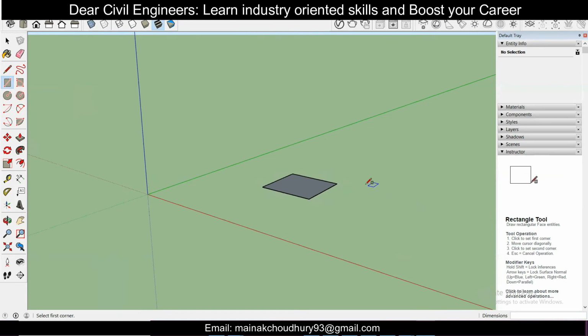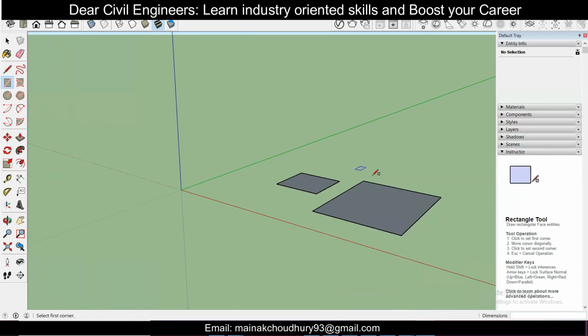And if you want a perfect shape, or a golden shape, you just press shift, and you can see here a perfect golden section will be created. You can create a square or particular fixed ratio rectangles using the shift option like this. Okay, so this is pretty helpful. So you have learned how to create rectangles along different axes, and how to give the sizes of this rectangle. So it's pretty simple.